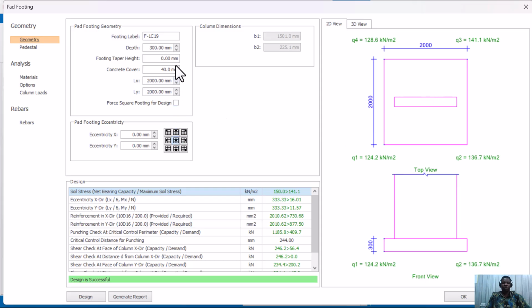If it's what you want to adjust, like what I've been doing, you can adjust it and check all your area and check the design, right? In as much as the design is provided, you have to check the area required against the area provided, because when the area required is very close to the area provided, then you need to upgrade the reinforcement or increase the section of the footing, okay, so that you'll be in a safe condition.